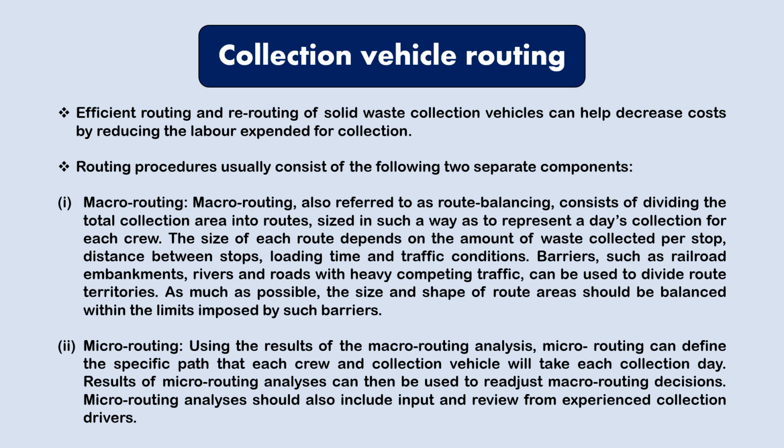It basically means that we will divide the total collection area into routes, and divide all the routes among different crews, and the size of each route actually depends on the amount of waste collected per stop, the distance between the stops, loading and traffic conditions also.